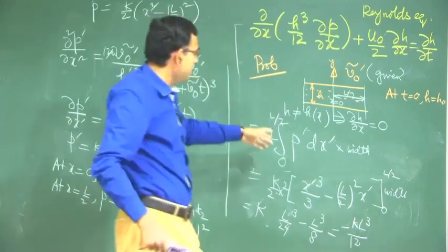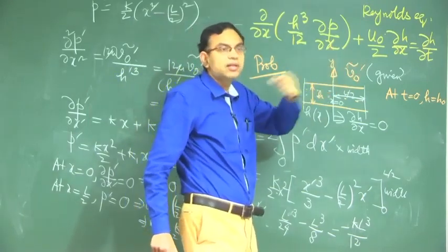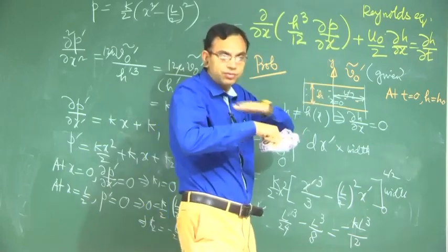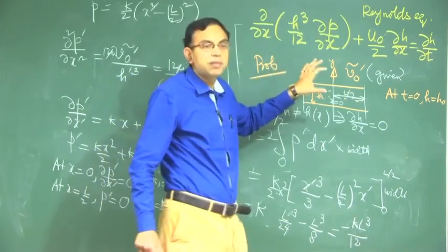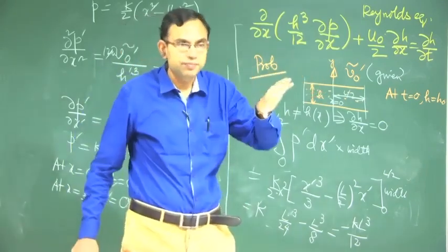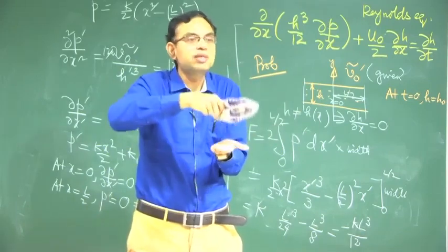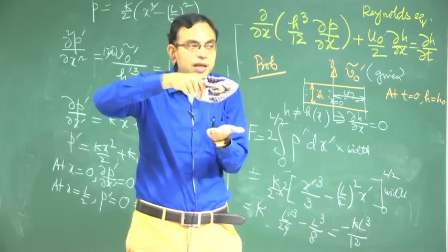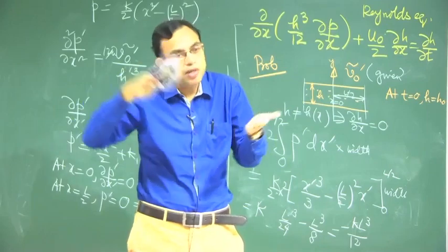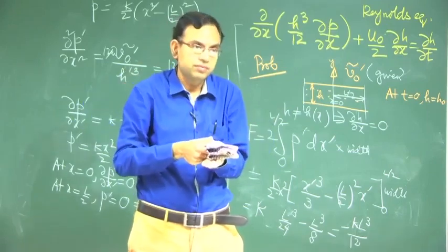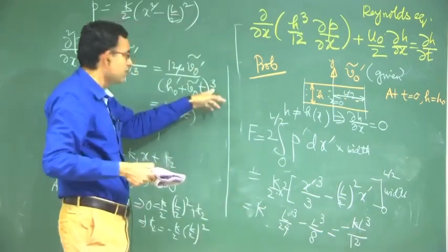On top of that, intermolecular forces will also start acting, the van der Waals and other forces will come into play when the plates are sufficiently close. This is a very interesting problem called the adhesive problem. You bring the two surfaces very close to each other, and in the limiting gap when the two plates have almost touched each other, it is virtually impossible to make them touch, because of the divergence of the force with 1 by h cube.